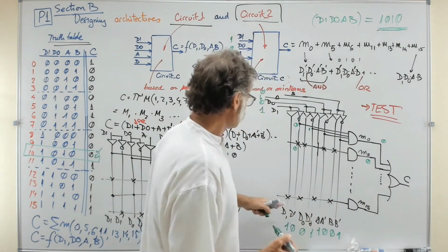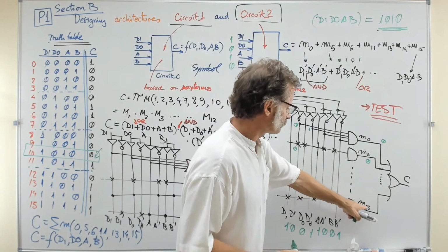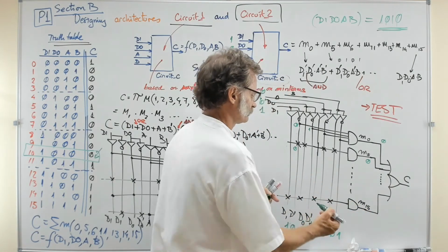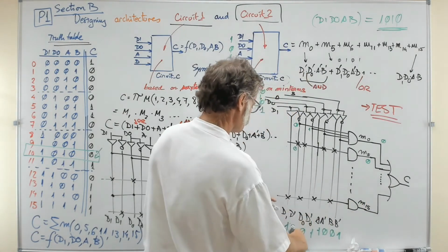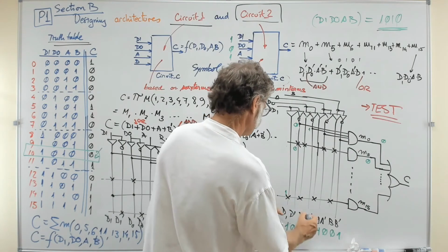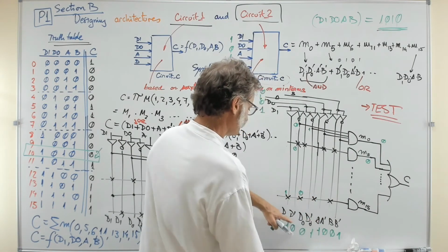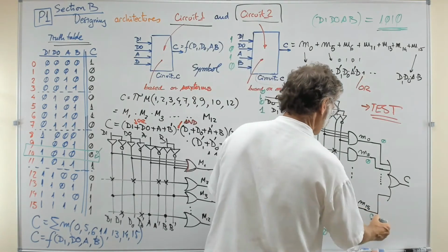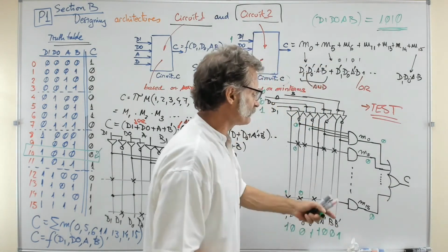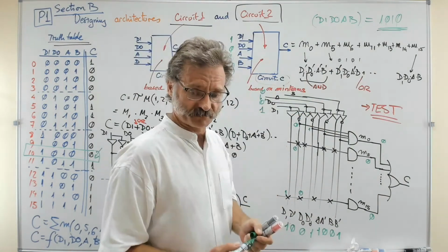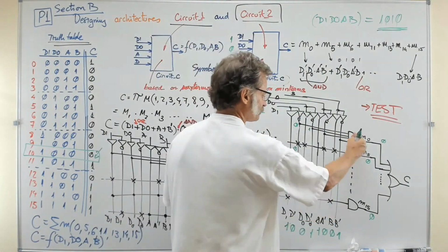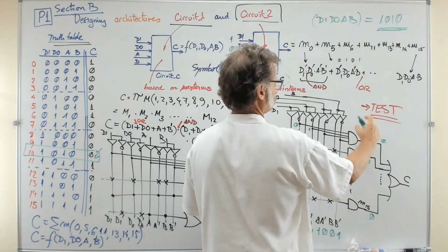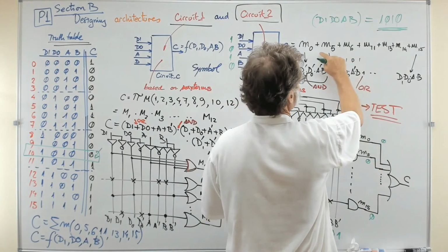And finally, the minterm 15. Well, the minterm 15 is going to be 1, that's all right, but you have here taking D0, which is 0, so you are generating another 0. It looks like that the 3 of them are 0. So what about the others? Well, it is better to finish the circuit, so instead of 3, you have them all, the 7 of them.